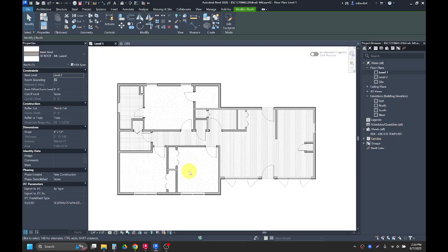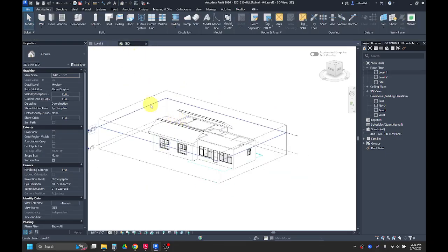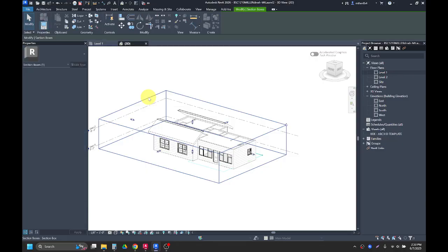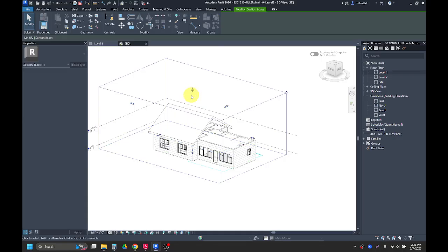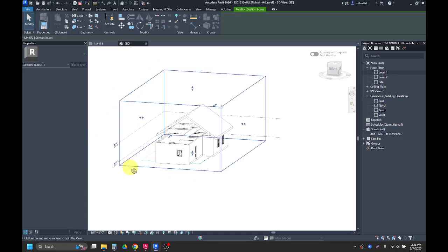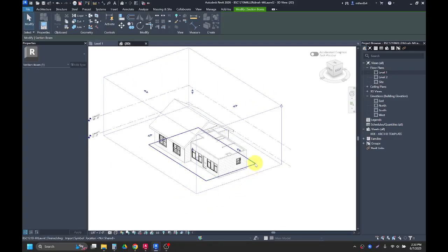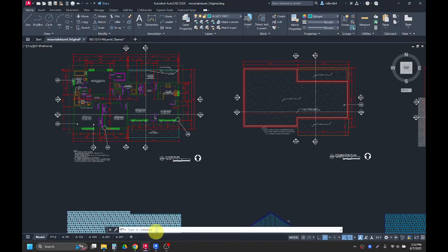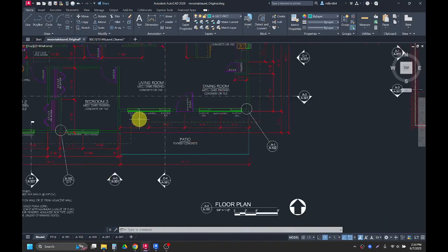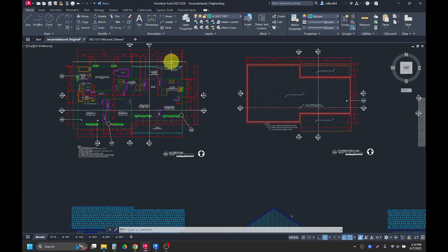It's not going to look like anything happened because I'm in my floor plan view. But when I go to my 3D view, I have a roof. Because I have my section box cutting part of it off, I just need to grab that and pull it up. So I've got a roof on part of my building. I'm going to add the other half of my roof with just a 2-foot overhang on this side. And on this side, I'm going to make it match to where that roof came out.